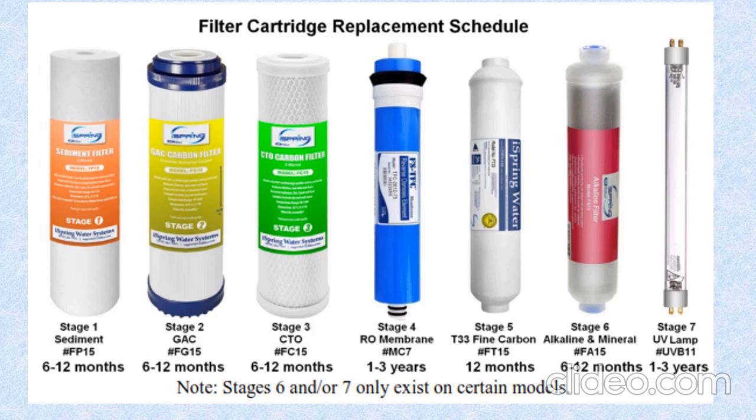And next, the most important one, is our own RO membrane, through which the water moves and where the complete purification process takes place. Then the water coming out of it goes into a post-carbon filter. The first one, stage 2, is called the pre-carbon filter, and stage 5 is called the post-carbon filter. Any fine particle still there will be filtered off here.